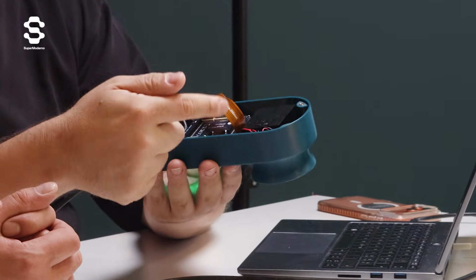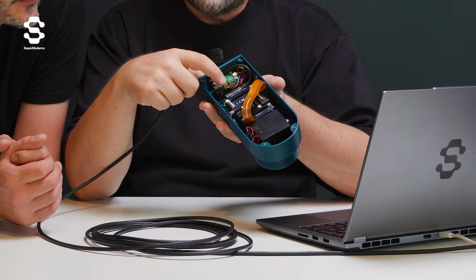So we're using the headphone output, and the rest of the circuit is made of this little Modulino here. This is just using a simple STM32 tiny microcontroller, which is using I2C as a common protocol, and it drives smart LEDs. So we built a little firmware where I can send simple messages and it will drive up to 25 LEDs with this particular firmware.